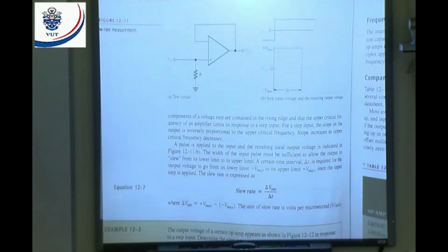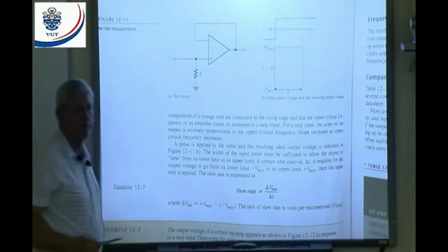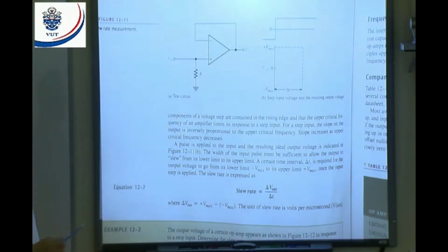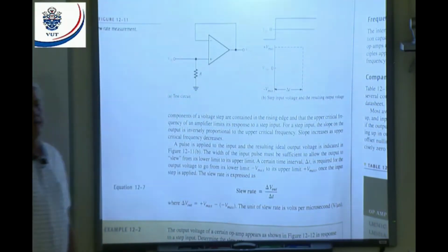Positive feedback or negative feedback? It's negative feedback. Why? Because we take from the output to my inverting input, all right? And there's a 180 degrees phase shift. That's why it's negative feedback. If I take this wire from there to that position there, then I will have positive feedback. And when you got positive feedback, the device will saturate, all right? That's why to decrease my gain, I will always apply negative feedback.